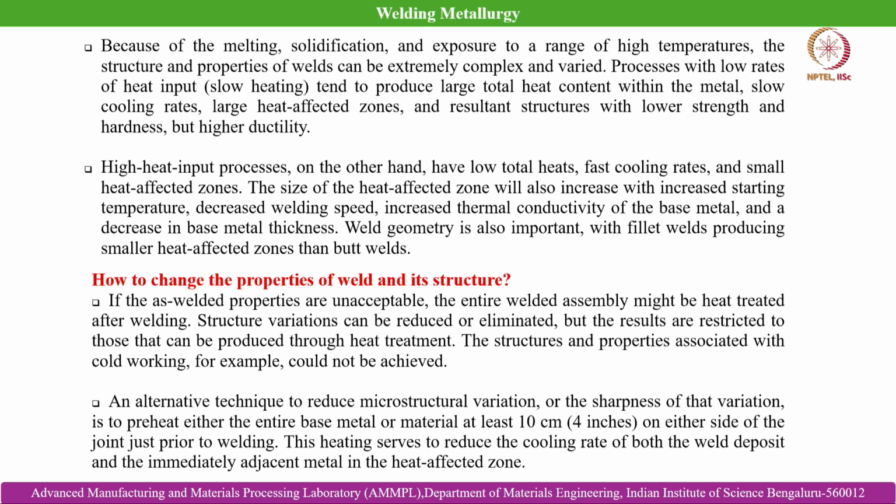However, if there is an intrinsic defect, like the defects which we have discussed in case of casting, which are also true in case of a weld joint formed in fusion welding, such as gas porosity or even slag inclusion, impurity entrapment, then it is very difficult to correct those by heat treatment alone. In that case we may even need to scrap the joint itself.